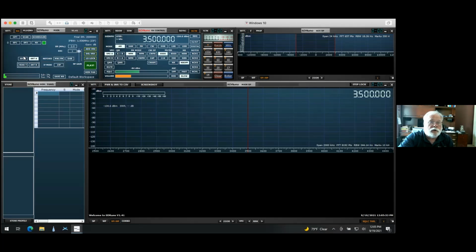If you have a device like an RSPdx or an RSPduo, in the main window you see here in the upper left, this is where you will select the input in use. I'm using antenna A, so antenna A is selected. What we'll want to do, at least initially, is start with the gain all the way to the top, and we will only reduce that if we get an overload indication here. This is also where you will set the sample rate, which determines how much of the spectrum you see in the main window. Whether or not we go more into that, I don't know.